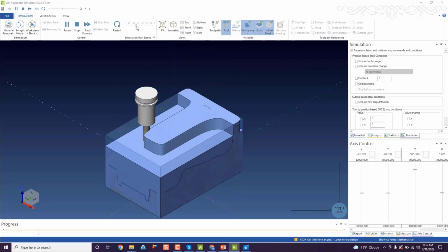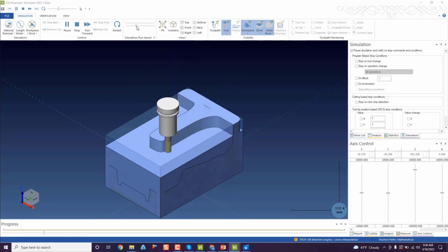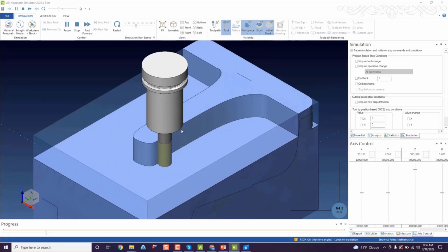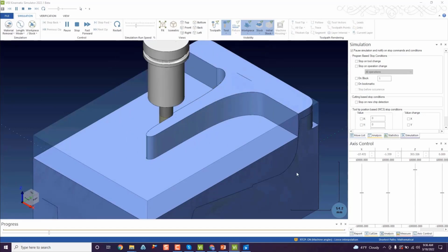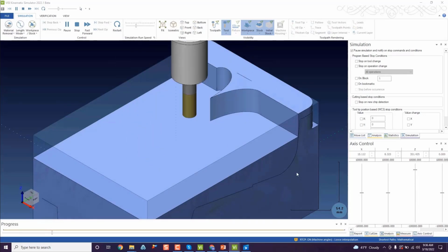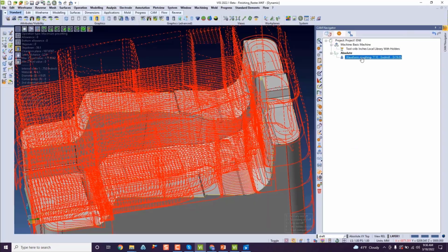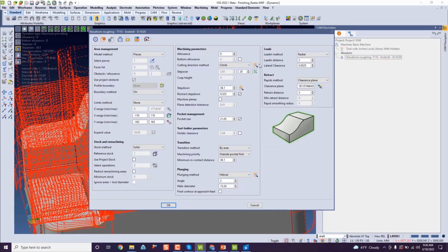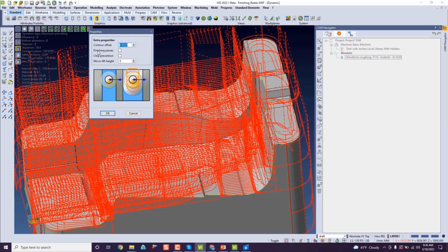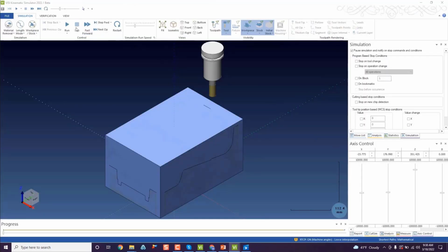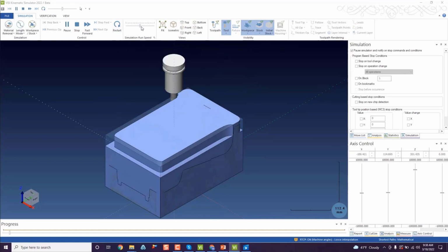As you know, loud harmonics can occur when you're cutting thin walls, depending on the depth of your cut. When the harmonics are happening, the tool is chattering against that thin wall, which means interrupted cuts, and that is never any good for your tool's life. This can cause chipping, and it could cause breaking of the tool. It is just something you want to avoid when you're cutting your material.